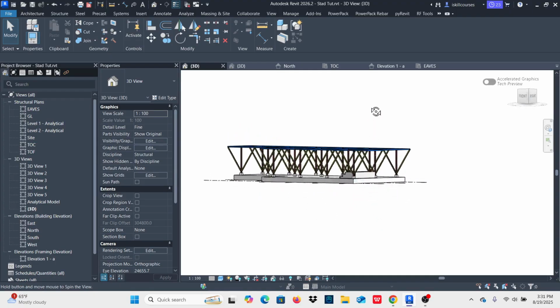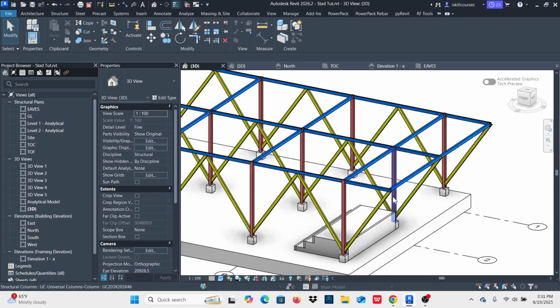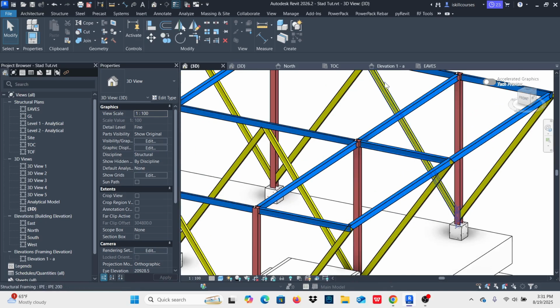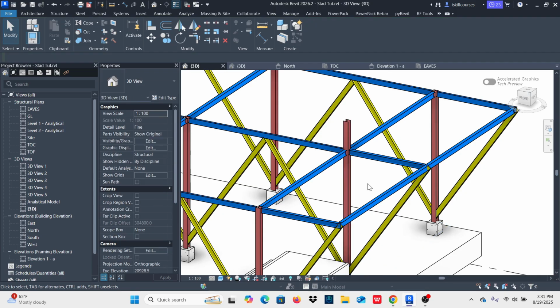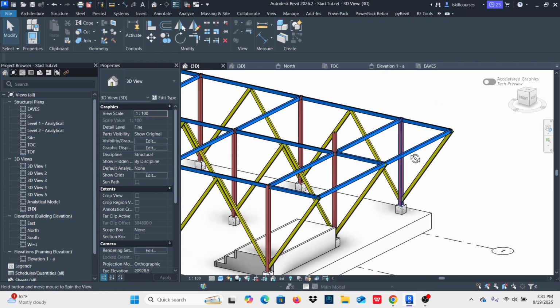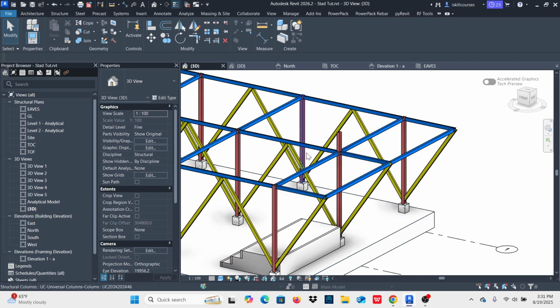Okay, so now the next thing that we can do here is to create the top part there. So I'll select this member and I'll extend this one by 1200. So the top offset, you can see this member ends all the way up to the eaves. The top offset, if I extend it by 2, I can have it like that.